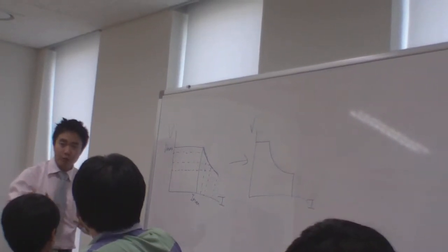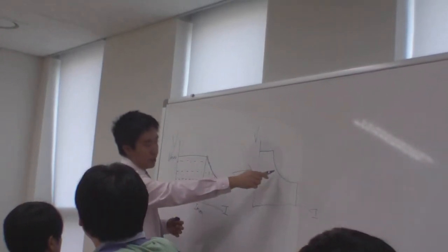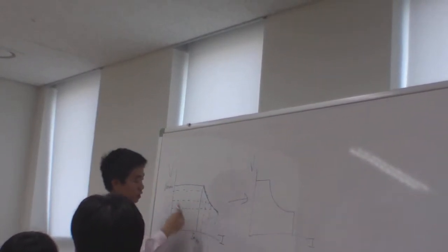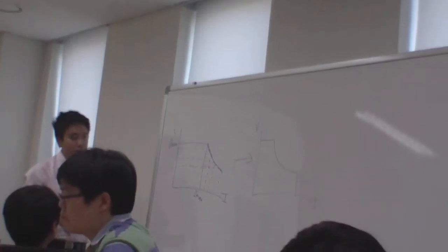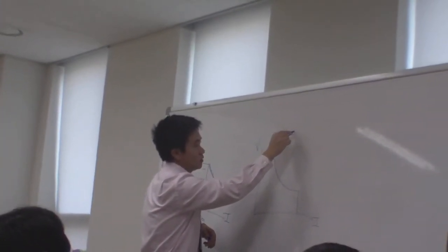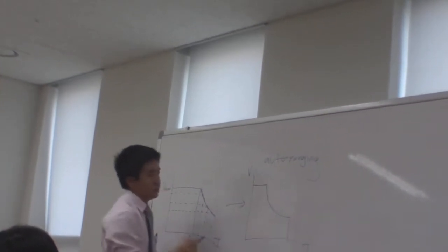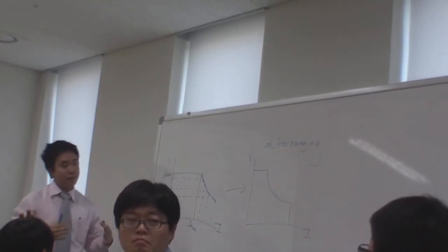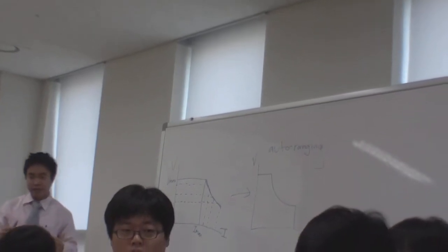So you don't have to use 2 power supplies, 3 power supplies, or 4 power supplies. You can use a single power supply and get all of these constant power curves, and all of these ranges that you want to use for the DC to DC converter. This is called auto ranging. So this is the auto ranging DC power supply output characteristic, and some of our modules have this output characteristic that you can use to test DC converters.